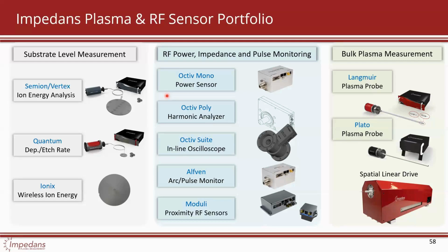The sensors that I've shown you today, the ones that you can mount, can be mounted on the substrate area that you're sputtering to, or directly on the sputtering target if you want. As long as you measure the ion energy distribution function and know your highest energy ion, you can set a high enough G2 blocking voltage to block all ions, but it will always block all ions. It won't discriminate by particular particles. Kindly share this paper? Will do.